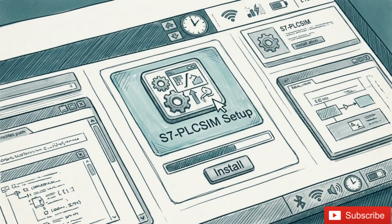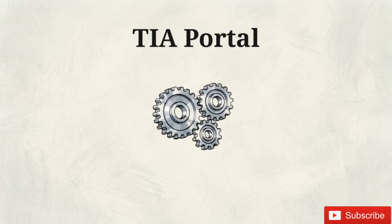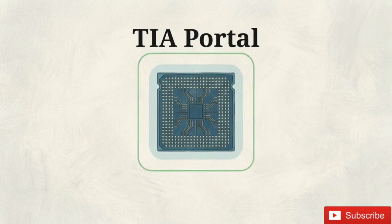Once your computer boots back up, open the S7 PLCSIM installer. Follow the exact same procedure. Select the typical installation path, finish the setup, and perform one last system restart. Without these activation keys and the PLCSIM module, the TIA Portal operates strictly as a text editor. The PLCSIM installation is what actually processes and executes your code.